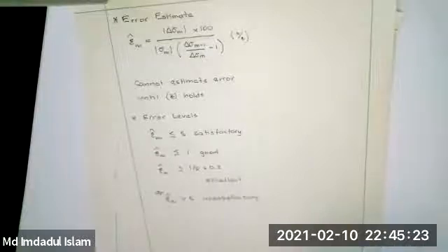A number of the books don't have that Shigley formula. The formula for the hoop stress is P R bar, the mean radius, divided by T. And for the longitudinal stress, it's P R divided by 2T. And a lot of the books don't have R bar, which is just lazy on the part of the authors writing them. Shigley introduced that, which is an improved estimate, about 1950, I think. So I think they copy from each other or something. But anyway, I don't know good mechanics and materials books that do this that well.